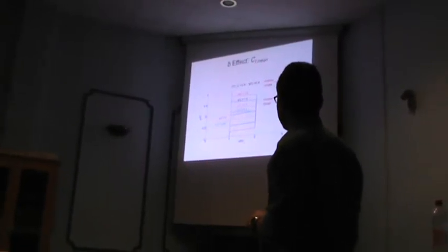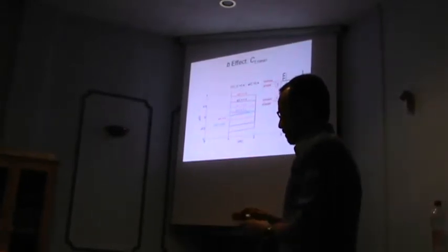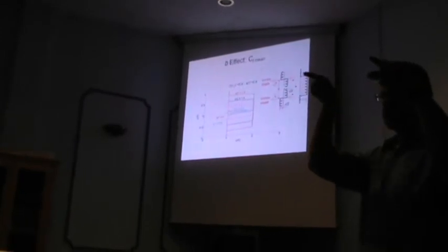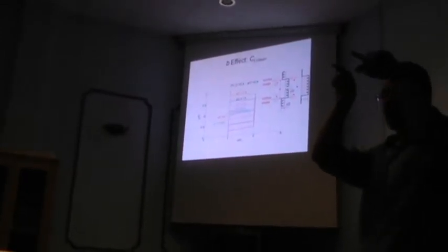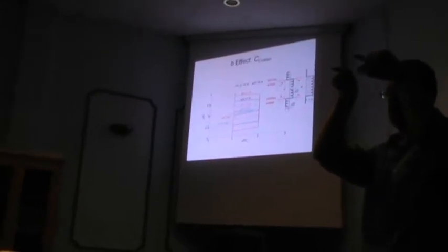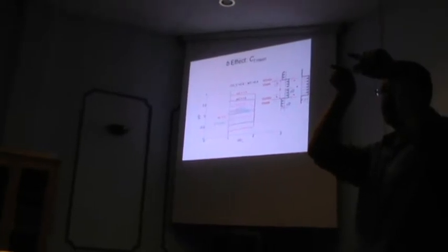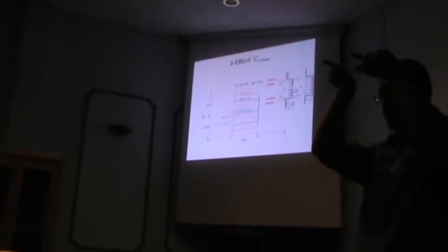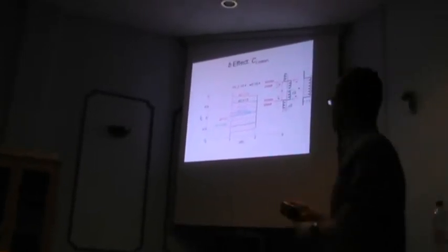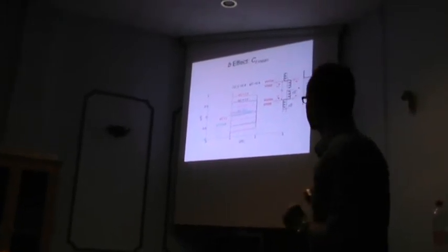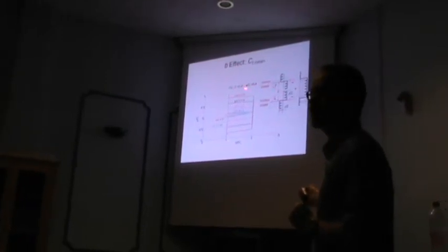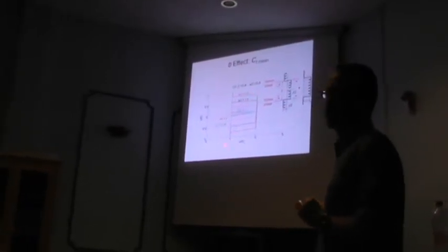So if you look at that and take a clue from this, you say, okay, I understand that I don't actually have a continuous distribution of vorticity. I have a vortex, vortex, vortex, vortex. But then you say, what if I calculate the equivalent circulation per unit length? So I take my gamma from the vortex and divide it by the spacing A, and call this my small gamma for my model. Then I have my gamma, 0.4, divided by 0.4. That's actually a 1, and this is exactly what this jump is.